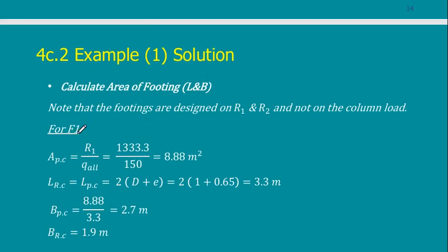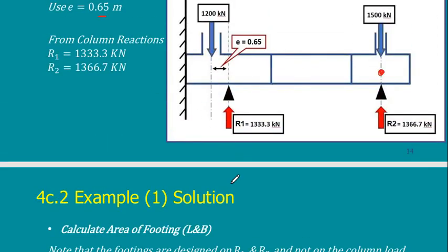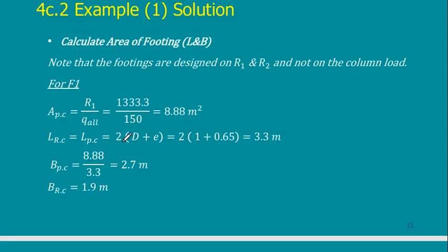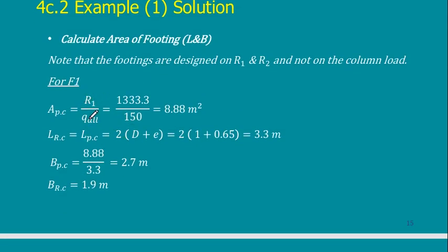I'm going to F1. F1 is the first footing. F2 is the second footing. Normal isolated footings, I'm going to skip it very quickly. The force divided by the bearing capacity, I get the area. This area is length by breadth. I calculate the length, assume any length, any breadth, assume it as any values you need to satisfy this example.